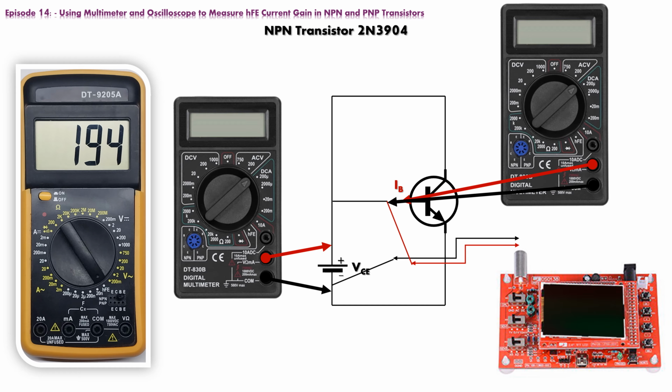Only problem is, that we cannot stick our probes directly into the slots of the hFE port on the multimeter. We need the transistor in, and the multimeter on, so there is no room to attach additional probes. Let's use a breadboard, and some DuPont wires, to mirror the hFE port from the multimeter onto the breadboard.